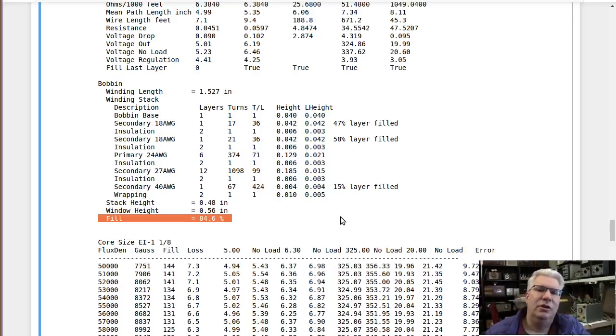And it allows you to create your designs and iterate very quickly, given the flexibility that you have in terms of choosing your flux density, your circular mils per amp, the wires that you have to choose from, the cores that you have. There's a lot of different things that are all involved in your decision. Whether or not you buy lamination, you get some specs for the flux density that it supports. You find something, you tear apart something from salvage, whatever. You should be able to use this tool and figure out your turns ratio. And if you're going to build your own coil winder, this thing is going to send the right codes over to Grbl.